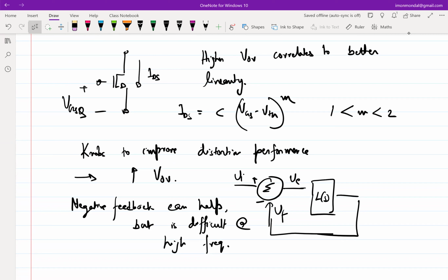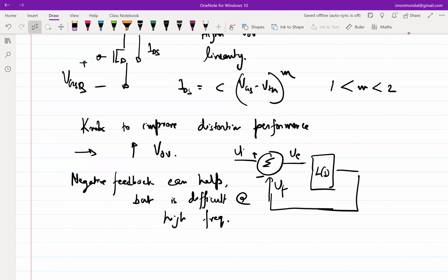Oh, that depends on the small signal. You have to find out the phase margin of the loop, right? That's what essentially phase margin is telling us. Phase or gain margin, assuming this is like a monotonically decreasing transfer function. For example, if VF is exactly 180 degrees out of phase with VI, then it's an oscillator, right?